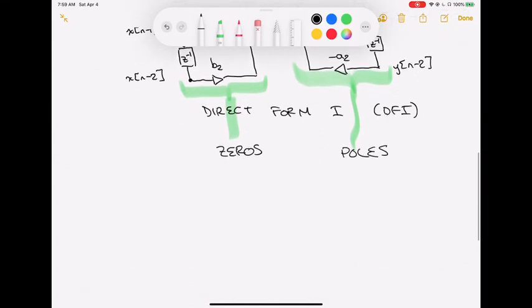So just like the direct form one, when we were doing continuous time system, we got this idea that zeros are going to be leading to the poles, and that ordering tends to reduce the likelihood of overflow. And so I'll say that that's a real happy face kind of an idea. That's a good quality of this particular structure.